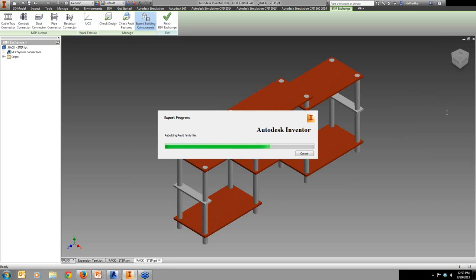And the shrink wrap, although it would automate the process, there were limitations. Like I had this experience where I had to export a pump out, and it did not do a very good job of pushing all those pieces out. So there are limitations to that process. So it comes down to the kind of file you are looking at. You really have to treat it on a case-by-case basis and then decide if shrink wrap might be a faster route, or setting it up with parameters would be a better route, because setting it up with parameters obviously will allow you to make it a parametric family in Revit. So there are benefits to this route as well.